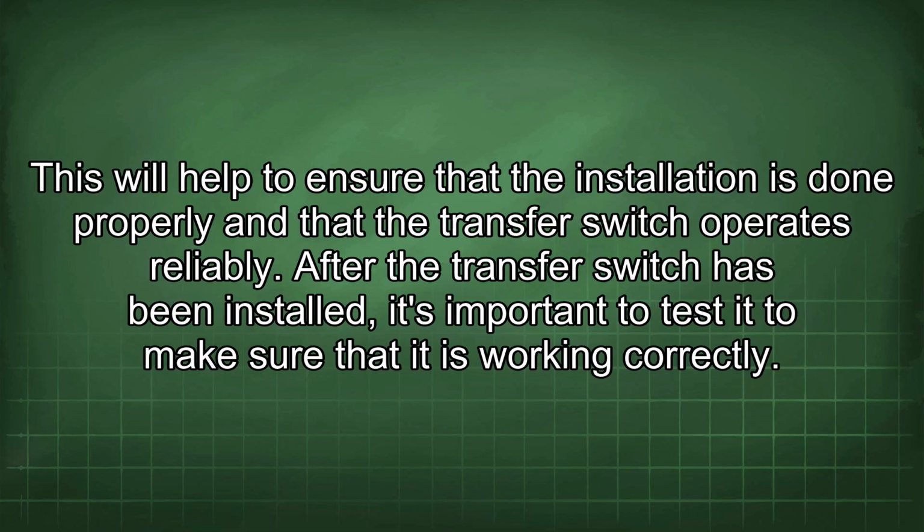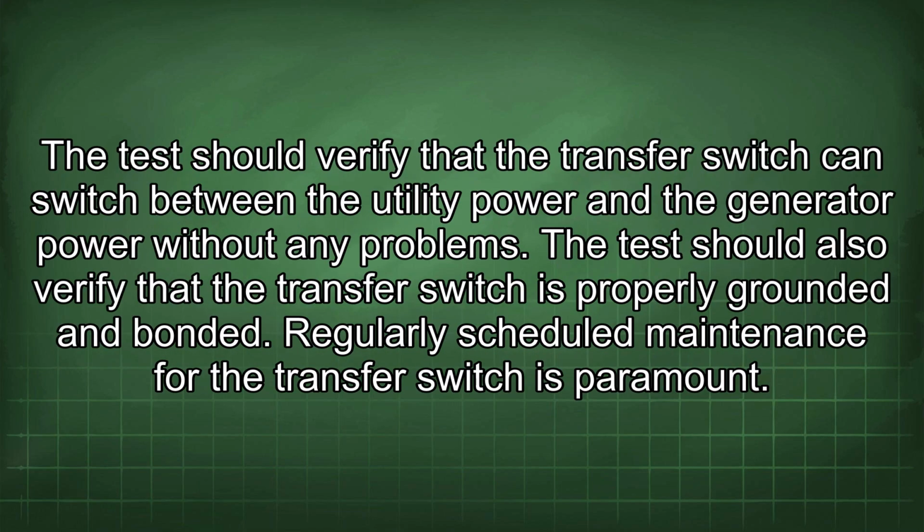After the transfer switch has been installed, it's important to test it to make sure that it is working correctly. The test should verify that the transfer switch can switch between the utility power and the generator power without any problems. The test should also verify that the transfer switch is properly grounded and bonded.